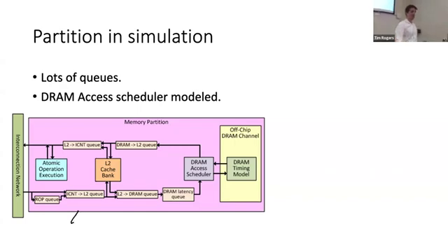So historically it means you have a lot of delays. Then you have a little queue here that is basically buffering everything that comes out of the interconnect. And then eventually, once you've got enough bandwidth at your L2, it'll check the L2 bank to see if it's there. If it is in the L2 bank, then it'll route it back, you have a cache hit in the L2, and it'll send the data back down to the L1s. If it was not, then it will go into another queue where it will wait for some time on the DRAM. And again, the L2 is way faster than the DRAM, right? So you need queues to buffer things. So then it will wait here.